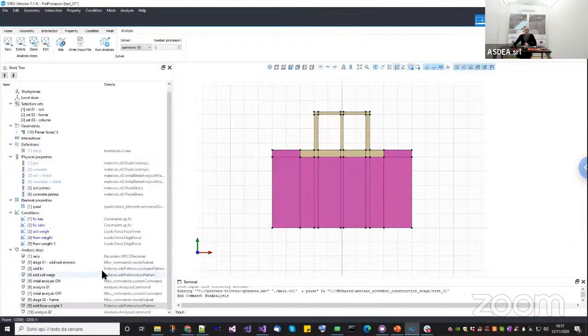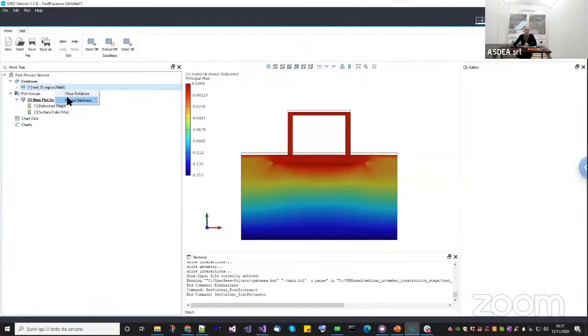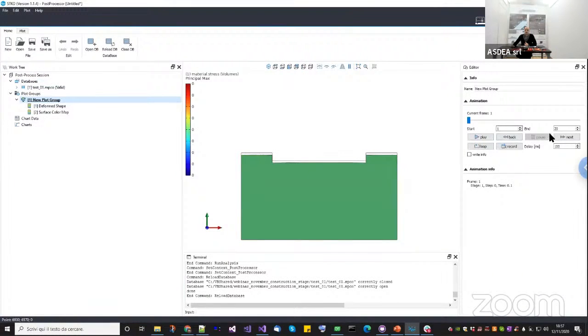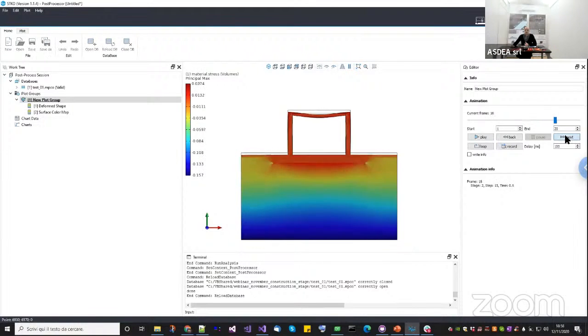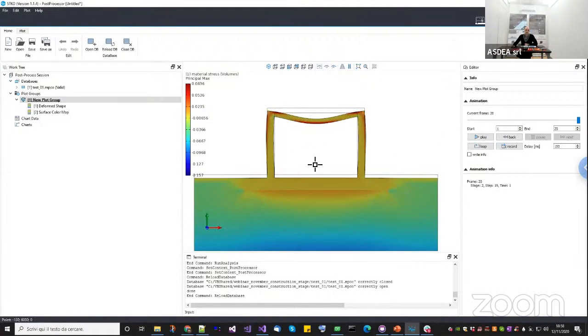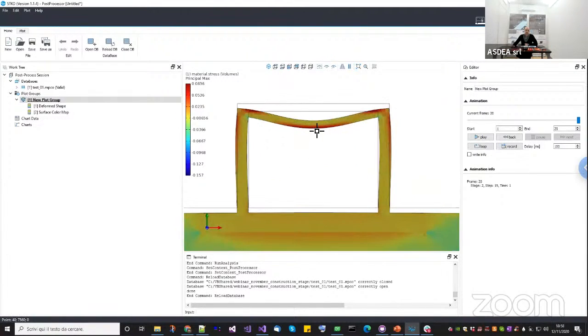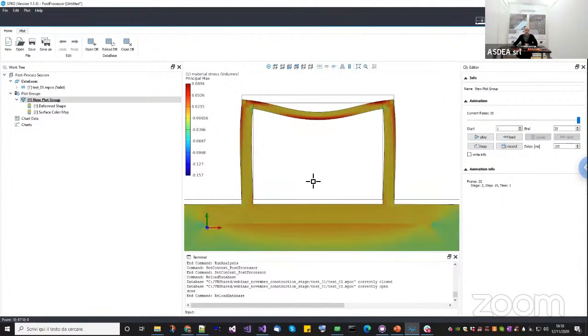Okay. Go back here. Okay, now basically you will see the formation of the first stage, then second stage plus its own load. Okay, perfect. Now this is fine. Now in the second stage, you will expect the new column to be placed here, but the new column will not be affected by the stress, actually by the load applied on the structure, because it will be applied here in the deformed configuration, so it will be stress-free.